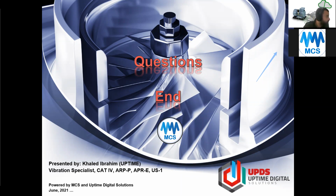The type of proximity probe used for the radial and thrust monitoring and speed monitoring. As we said, you have different types. When you do the design, you need to identify the type of the sensor. Is it for speed? Then you need to check the range of the speed, and the proximity probe under speed falls under speed.